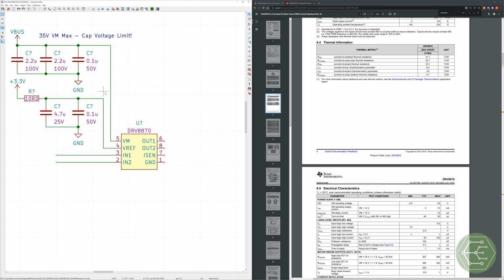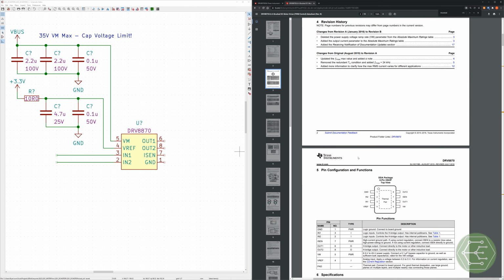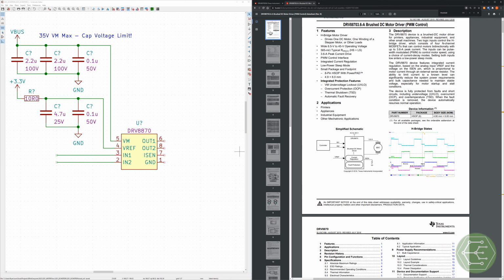That could be a pretty big issue, actually. Could catastrophically destroy all of the circuitry on this board. No repair possible. So I was like, great, we'll add a series resistor. That will at least limit the fault current coming through this IC back to the other domain. Cool. There's only one problem with that.